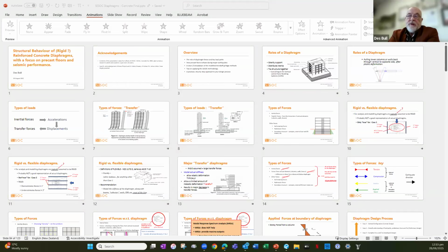It was originally introduced in New Zealand as a design tool because back in those days, people basically just had rigid diaphragm models. They didn't have the plates and so forth we could put in. So when you look at the evolution of these things, they sort of leapfrog over each other. If the practitioner understands that software and can actually interpret it correctly, great, go for it. If it gives a higher resolution and more confidence in where the load's going, absolutely. But the grillage analysis was developed for a situation when people did not have access to that sort of software. So by all means, if you've got better software, use it. Right.